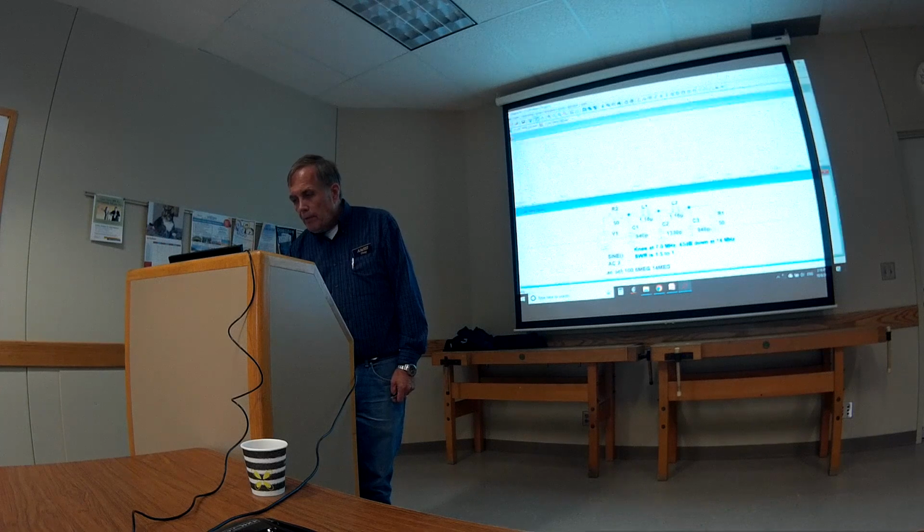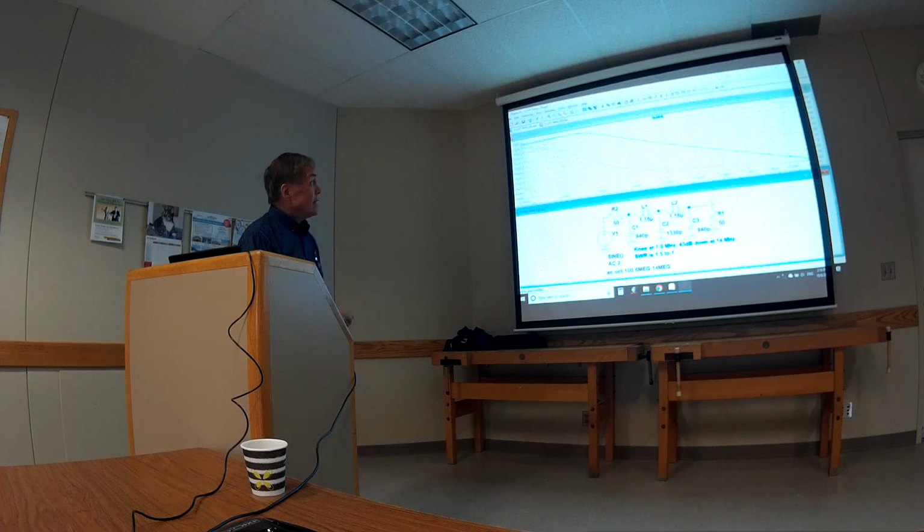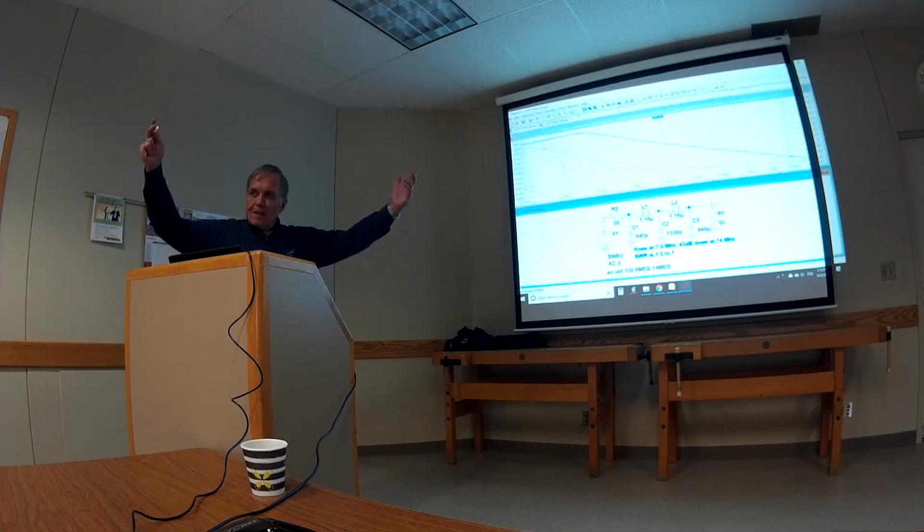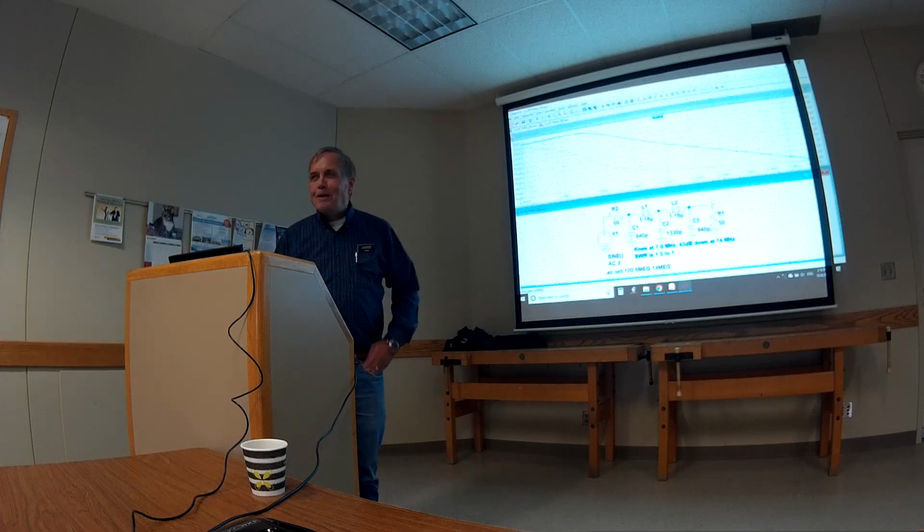So, I'm going to look at it right at the output, right at the antenna. Now, you can see that this one, the knee is at about 7 megahertz, give or take, pretty close, and it goes down at 14, stop the screen, it's about 43 dB down, which is the magic number. That's what the FCC requires, that the second harmonic be 43 dB down.